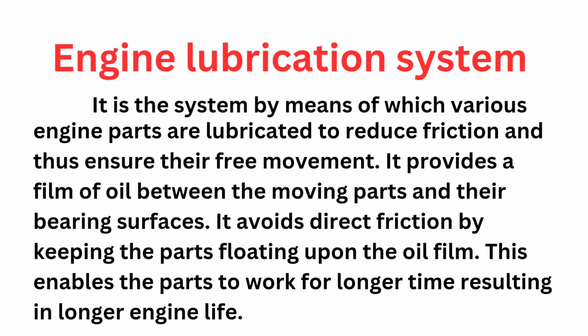It is the system by means of which various engine parts are lubricated to reduce friction and thus ensure their free movement. It provides a film of oil between the moving parts and their bearing surfaces. It avoids direct friction by keeping the parts floating upon the oil film. This enables the parts to work for longer time, resulting in longer engine life.